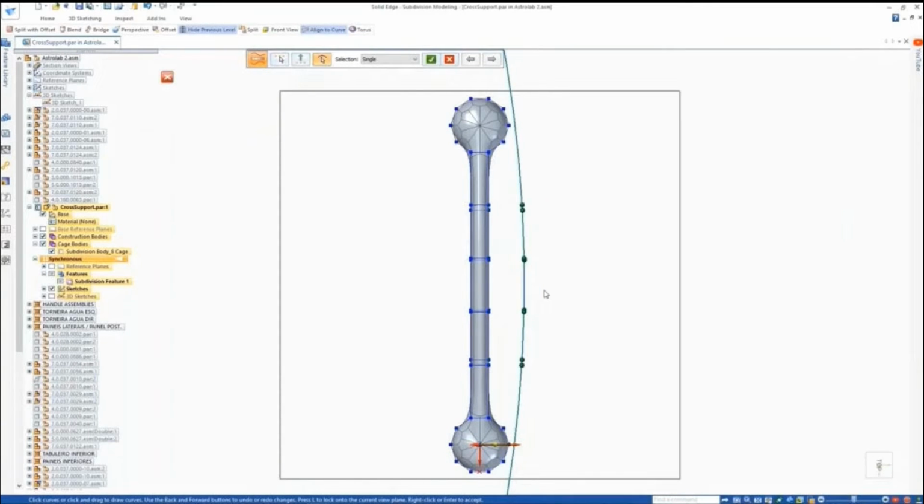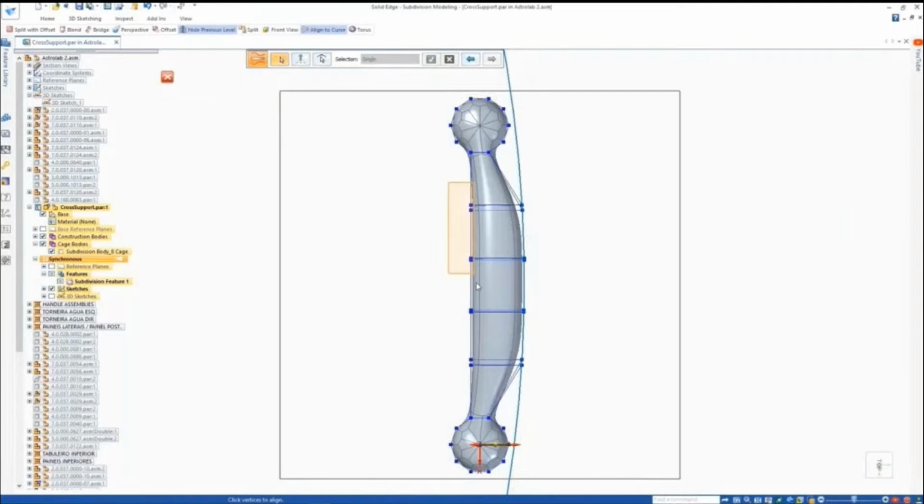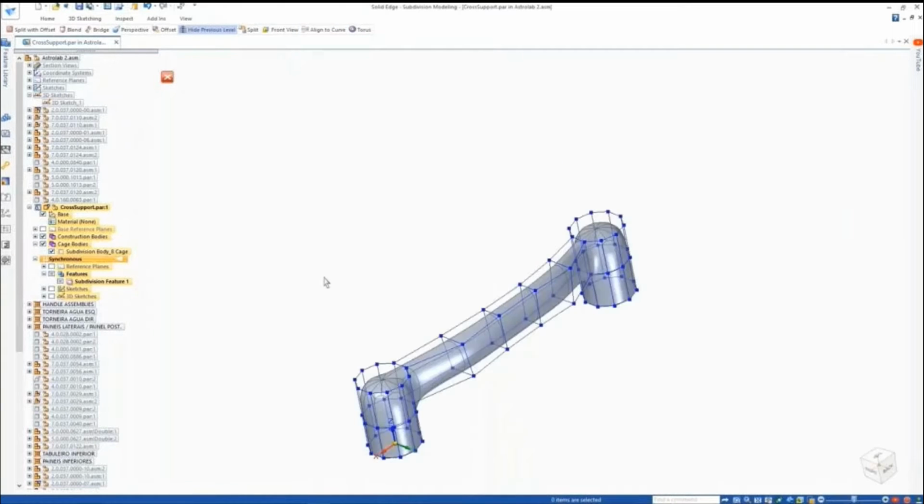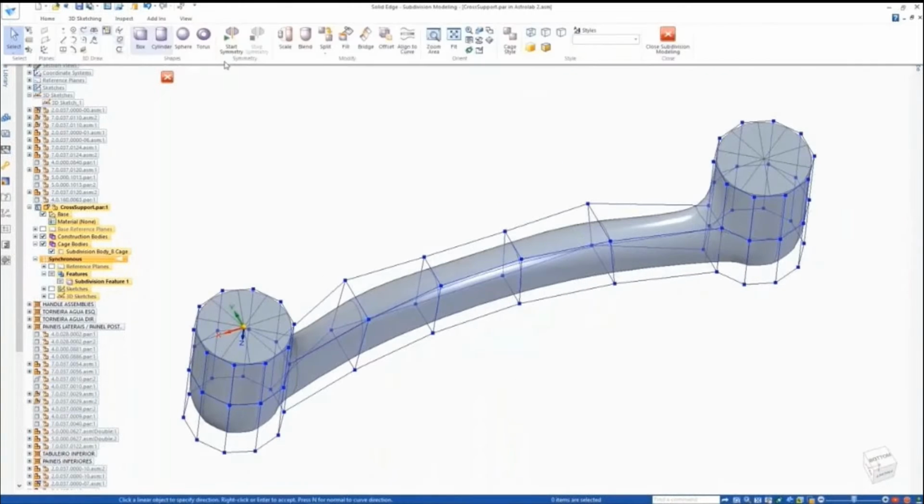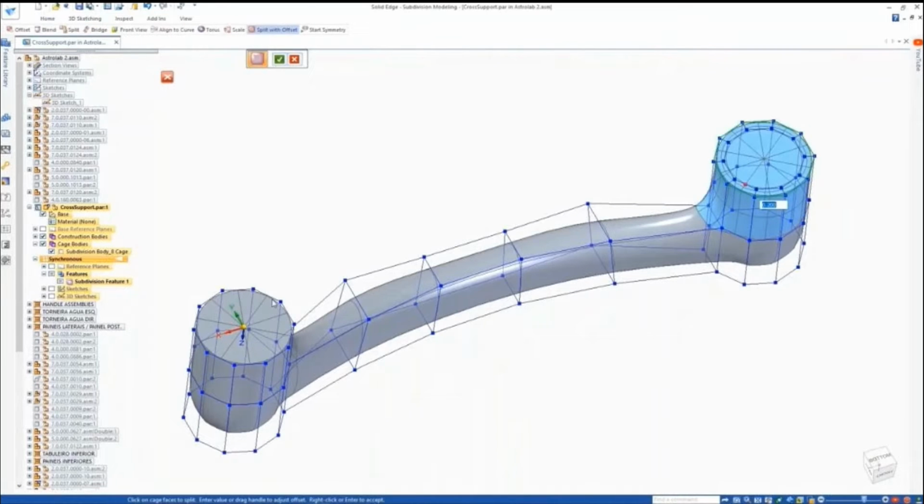During this process, it's possible to manually define a spline curve or even use gestures by clicking and dragging to fluidly adjust the form as required. Split with offset is another option that greatly speeds up the process of adding detail to a face by offsetting it inwards. This allows us to push the resulting faces to create some cutouts for the rubber feet on the machine.